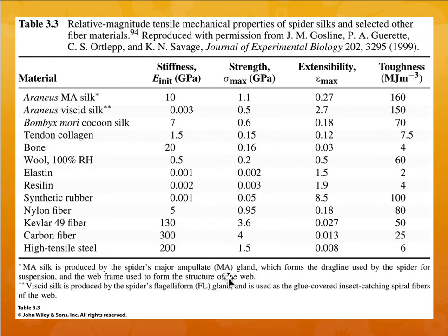And the other advantage is that the density of these materials is much lower than that of high strength materials such as high tensile strength steel. So you do not need to increase the weight of your component to get it to withstand the same kind of loads or tensile stresses. Which means that you can strengthen the material, but you don't have to increase the weight of your component. So that is the big advantage with composites.